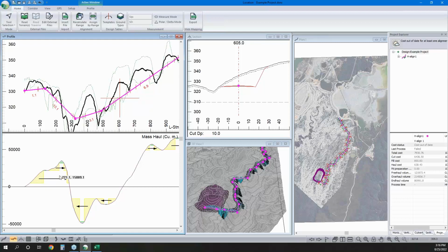So the general rule of thumb with glancing at a MassHaul diagram, and this kind of leads into some of the imperfections of a MassHaul diagram, is this is indicating that that material gets moved ahead. So we're creating a surplus, then we're creating a deficit. We're above the zero line, so it makes sense to take that and put that there.